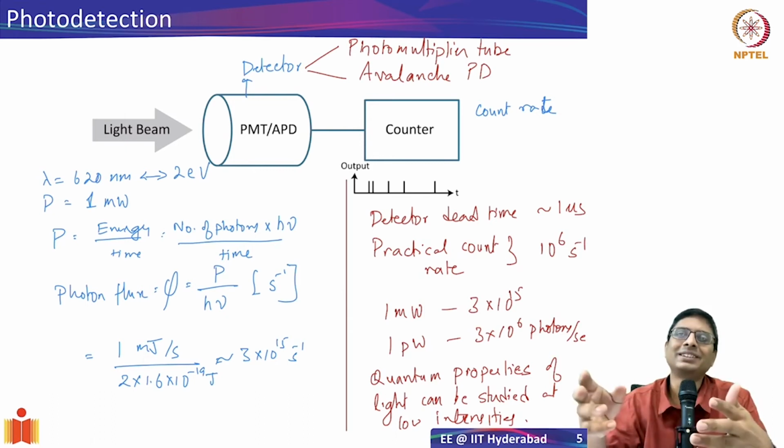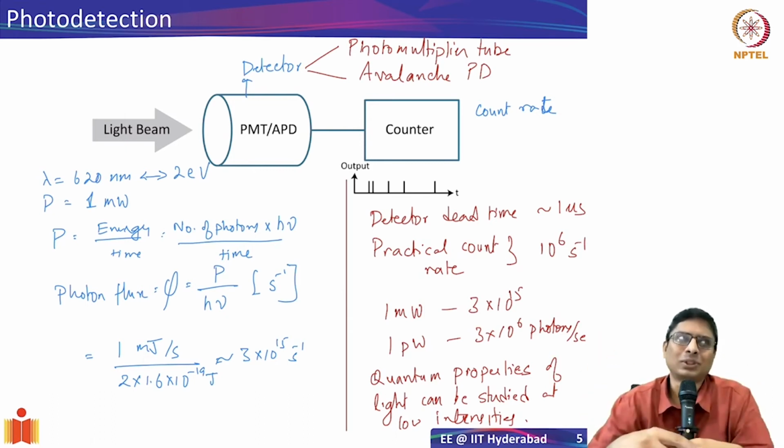There's no way. I mean, it's like, what? I don't even know what 0.1 attojoules feels like. Right? 0.1 attojoules, can you sense it with your hand or something? It's very, very difficult. You need an extremely sensitive detector. So if you want to have such a detector, the only way to go around that is by using the avalanche process or the multiplication process.